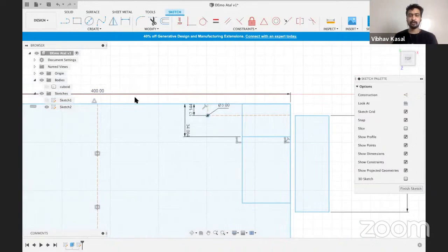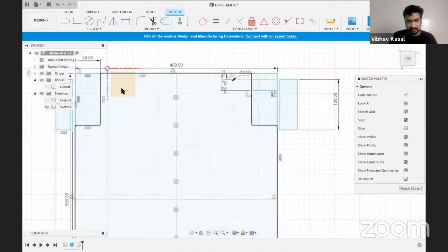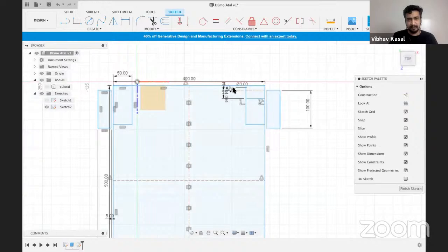And for this, you have to know what the clamps and the mounting holes of that clamp are. The clamp is that L clamp that you get, wherein you put the motor and you put nuts and bolts. Instead of drilling it using a drill bit and a tool, I'm getting this sheet laser cut in this shape with the holes also. So I can simply connect the motor and the L clamp.